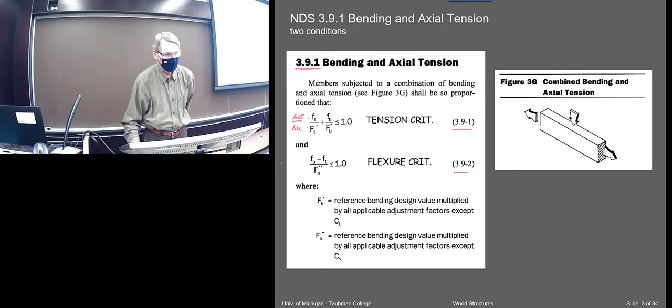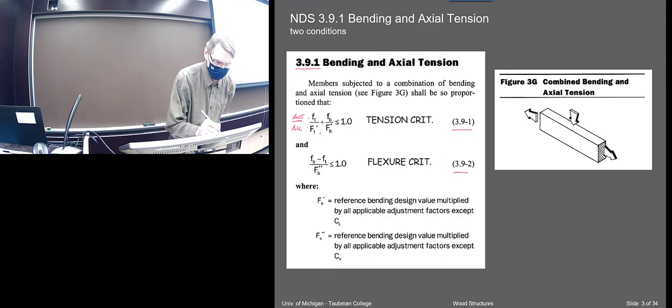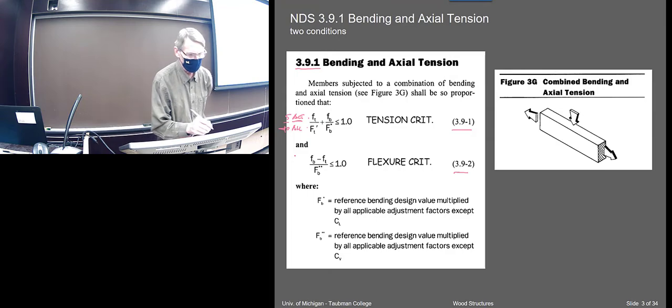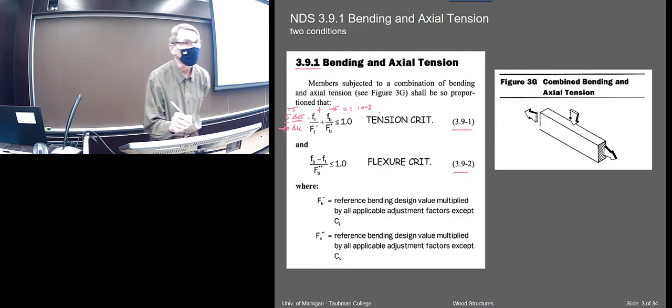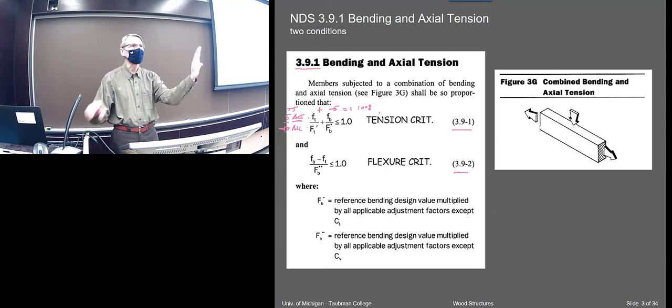If this was a ratio of, say, 5 to 10, I don't know what those are in, kips or ksi, some ratio that would come out to be 0.5, and if this one was similarly 0.5, they'd add up to equal 1, and that would represent 100% of the stress capacity, right? So you're taking it by part.